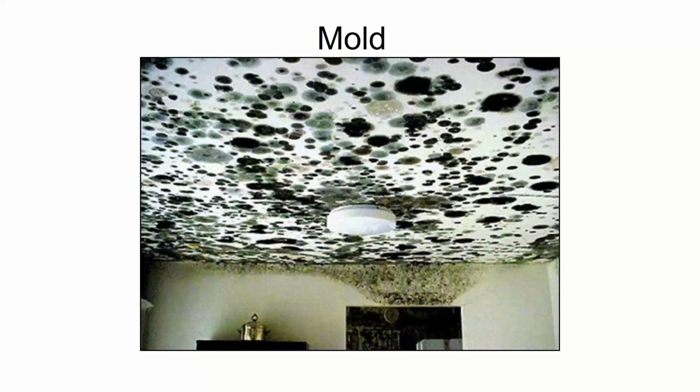Sources of water. So obviously in this picture, I don't know if you can see my little laser pointer here. Obviously the ceiling's a disaster at this particular building, this house. Obviously total disaster. The walls over here don't look bad at all. They look fine, but it's almost like it's flowing, right? Almost like there's a curvature to it. So there's probably some kind of water in this attic, maybe a roof leak or something like that, and the water is finding its way down to the ground, and this happens to be the pathway that it's getting down.